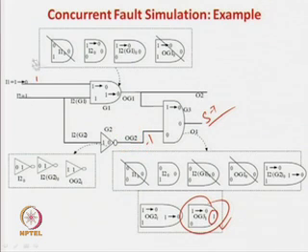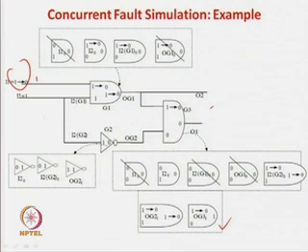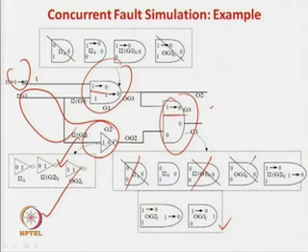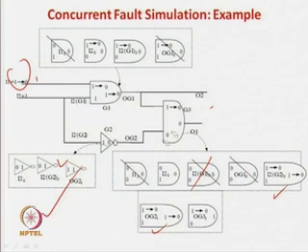So, what we have done basically by this signal change, this is a signal change which has happened, which is not affecting this gate in any way. So, directly you retain all the gates without doing anything, but for this gate and for this gate there are some changes, this is the signal change that has happened. So, based on that you find that these gates get deleted, because here the signal after this change will become 0 0 0 and these gates will also become 0 0 0, which becomes equivalent to this. So, these are dropped, but for this one and this one they are retained because there is a signal change. So, now you can easily derive which are the faults that can be detected over this.